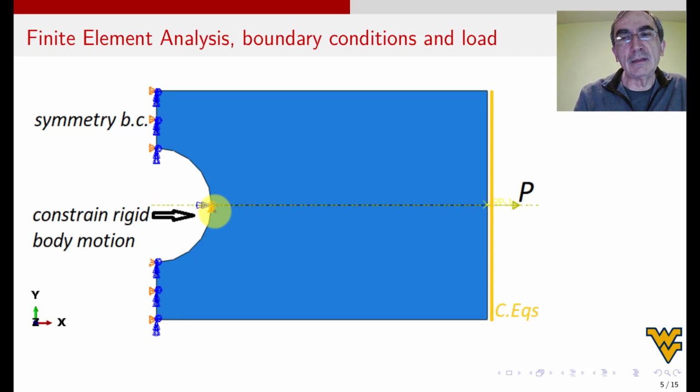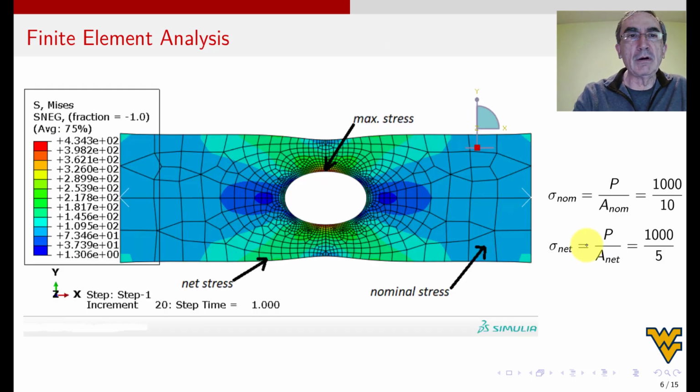Okay, so with that, I have set up the model and then I run it and I calculate the stresses, all right? So what we do is we go here. And so now here we have the bar deformed and with the stresses. The first thing you notice is how come you say you're going to calculate on half, but now you have the whole bar. Well, this is a trick, because since the solution is symmetric, there is a feature that you can just select and say plot symmetrically and it will fake this one. So this is a mirror copy of the one on the right. It's put on the left, yes, for your enjoyment, to make it pretty.